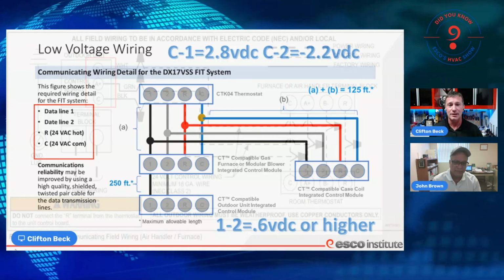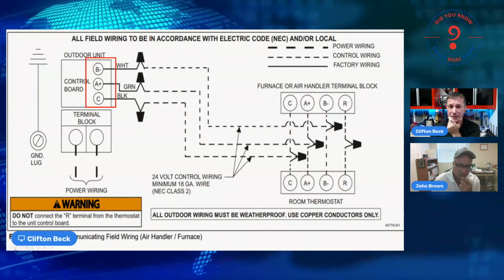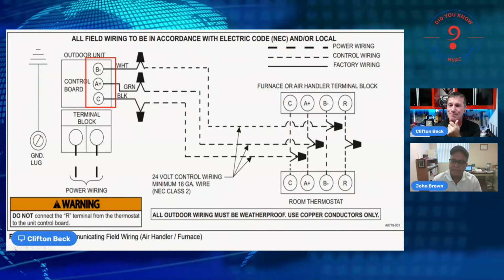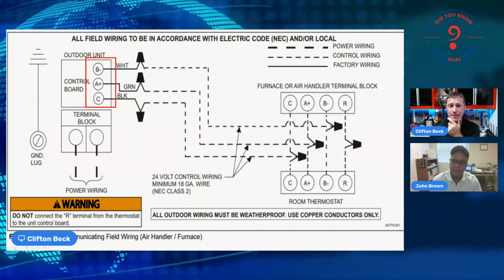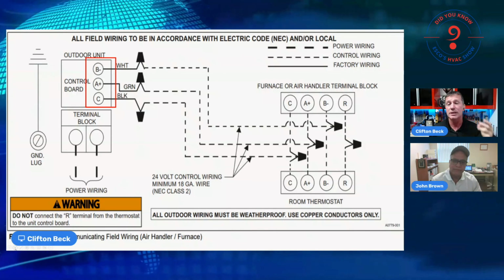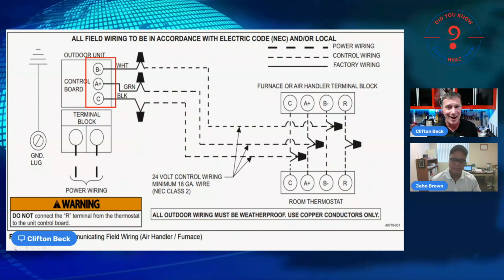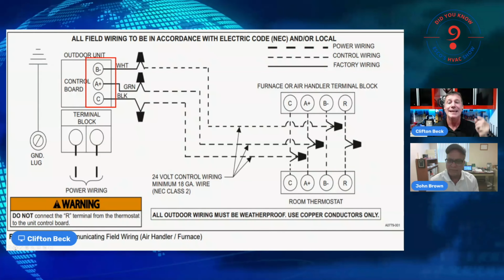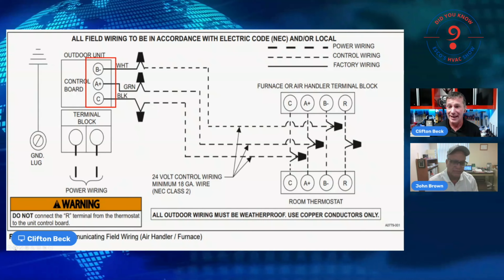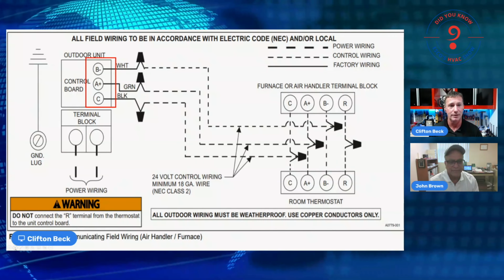Well, let's look at another manufacturer. If I look at this wiring diagram, I go, my goodness. I have another positive and negative signal, and I'm using a common, so a ground reference point. So this particular manufacturer is using 3 wires. It is using common, which is a grounded common. So that is our ground reference point. It has a positive signal on A in reference to ground and a negative signal on B in reference to ground.